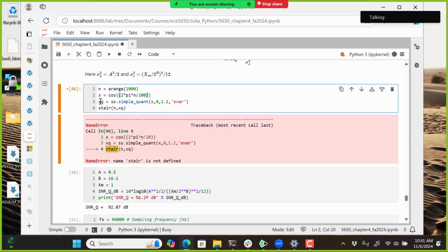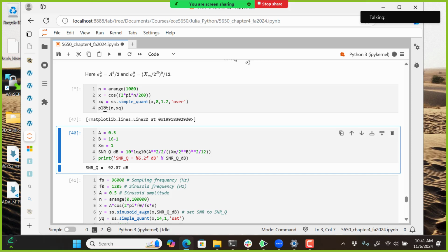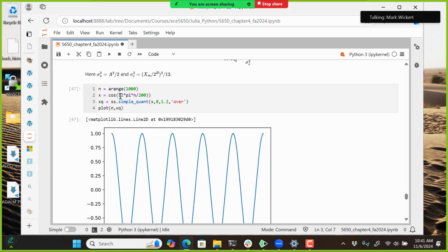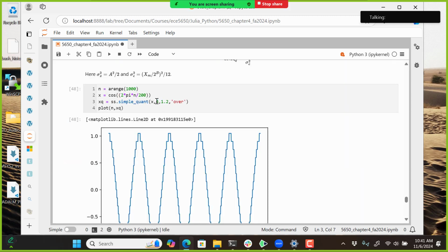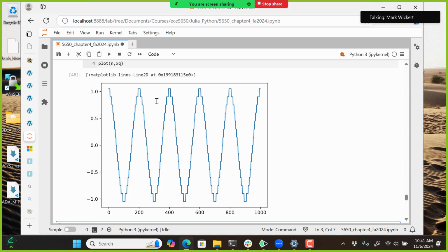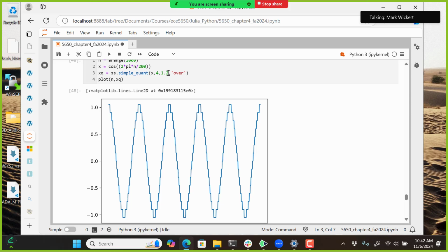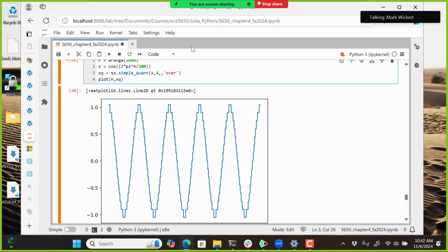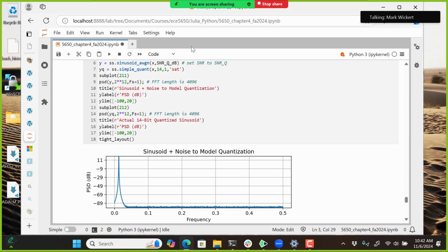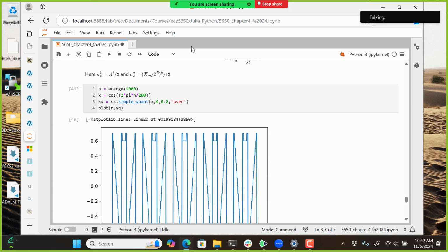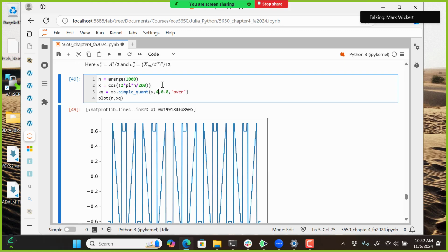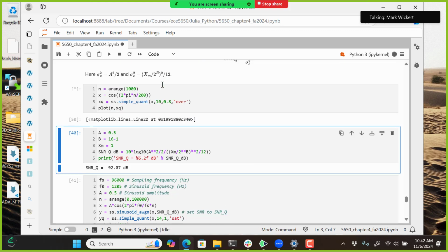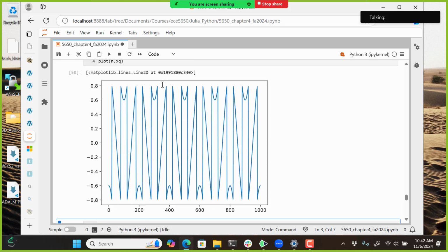Okay, so now I'm going to purposefully take this down to, say, 4. And now you can see that it is indeed quantizing. And now the disastrous thing that will happen if I only make this 0.08, now we're getting the overflow, so it's becoming negative rather than positive. And if I even took this back up to, say, 10 bits, we're still getting the overflow, which is not at all good. It's very disastrous. If I set this at 0.95, we'll still see the overflow occurring.